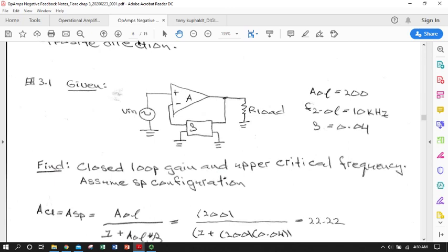So let's apply that to a hypothetical real circuit. So here's our kind of prototypical series parallel negative feedback op amp, and we know it's series parallel because we have our signal coming in and it doesn't branch. It's in series with the op amp, no parallel branches, but our output signal has a branch. It has a parallel configuration. It can either go through the feedback network or out to the load. So series parallel. So we know we can use the formulas we just derived.